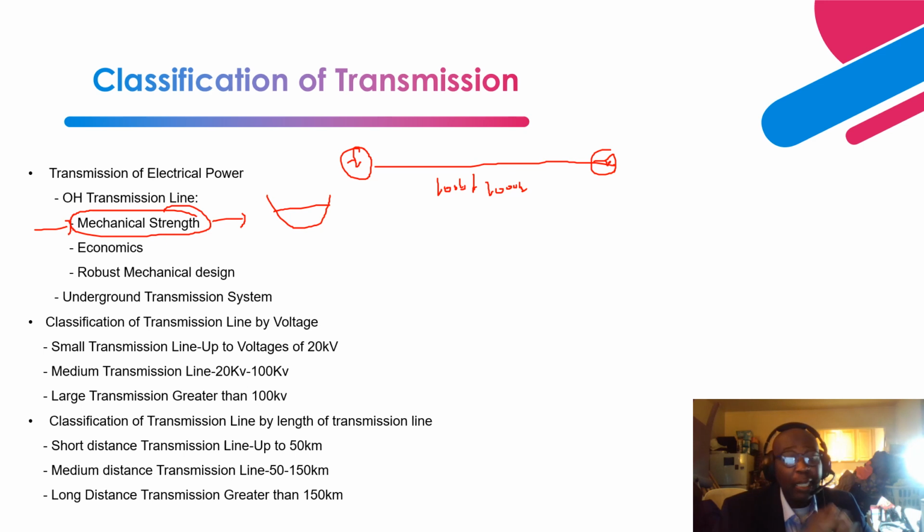Also, if you have excessive wind velocity, it can cause something called conductor galloping or conductor clashing, where one conductor from another phase can clash into the other, basically causing a temporary short circuit.